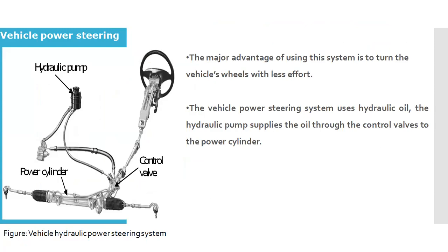The major advantage of using this system is to turn the vehicle's wheel with less effort. If I compare the vehicles which we are driving, the cars and all, the concept of power steering comes into application. It has different systems like the hydraulic pump, the power cylinder, and the control valve. Whenever you are driving a car with power steering, that is also based on the hydraulic system, and its major advantage is that it will turn the vehicle with less effort.